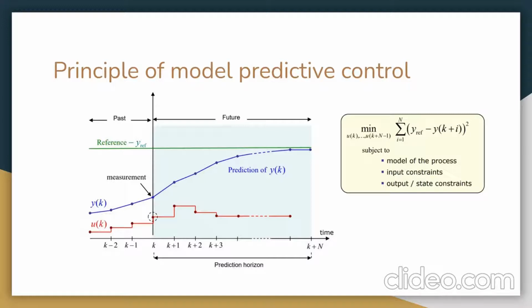And since the model cannot be perfectly accurate, only the first control step is applied, and the current state that results from applying that control is measured and passed as feedback to the controller. On the next step, MPC takes the measured state as a starting state, solves the problem again and generates a new plan, starting from that measured state.